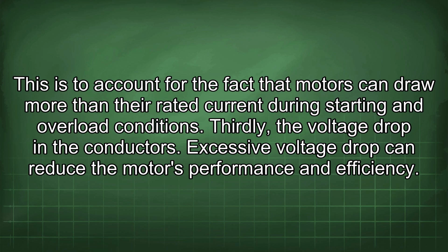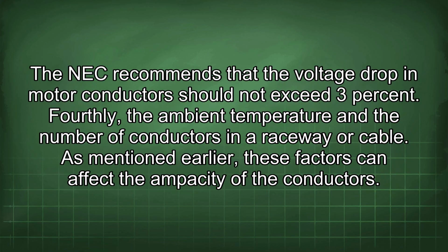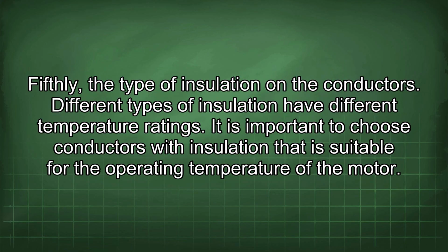Excessive voltage drop can reduce the motor's performance and efficiency. The NEC recommends that the voltage drop in motor conductors should not exceed 3%. Fourthly, the ambient temperature and the number of conductors in a raceway or cable. As mentioned earlier, these factors can affect the ampacity of the conductors. Fifthly, the type of insulation on the conductors. Different types of insulation have different temperature ratings.